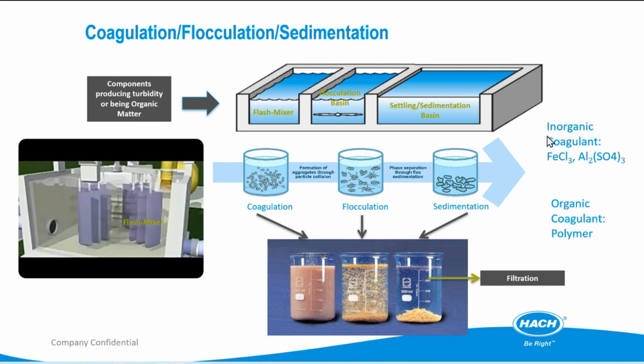That's why we need to dose the chemical, the salt of iron and aluminum, which is positive charge, to eliminate the negative charge. That's how the small particles can settle down, because we already eliminate the negative charge to have a neutral charge so that the small particles can settle down. That's the theory of the coagulation and flocculation process.